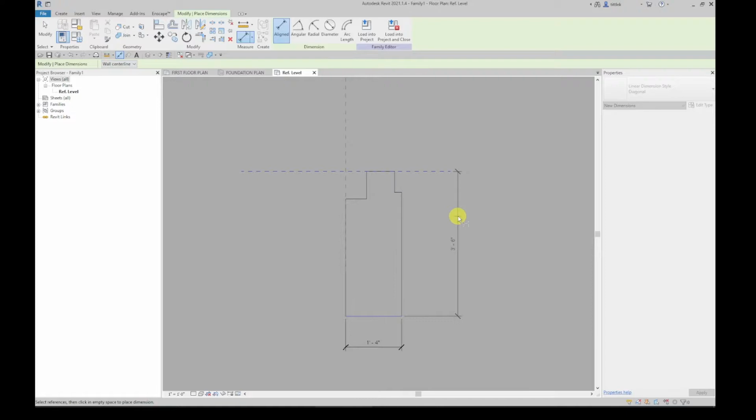this face. My slab ledge is actually going to be, here, let me select that, make that 1 inch, and it's going to be 5 inches deep because our slab is 5 inches, right? So oops, I'm selecting the wrong thing. Click on that. Oops. Okay.